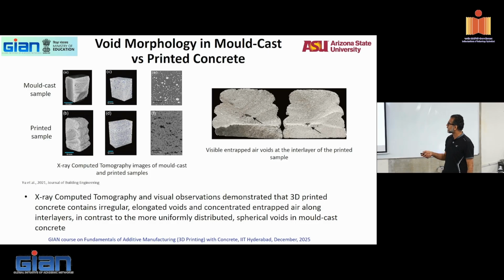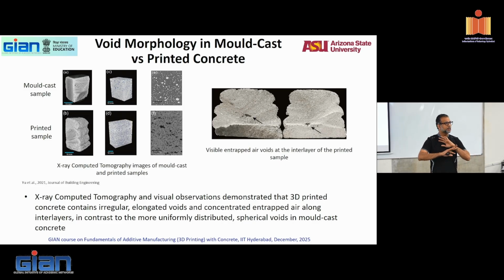But again, there's lots of work on X-ray computed tomography, looking at void distribution within concrete. The idea is to show that while in a regular concrete your voids will be uniformly distributed, now you will see preferential distribution of voids in the inner layer zone.